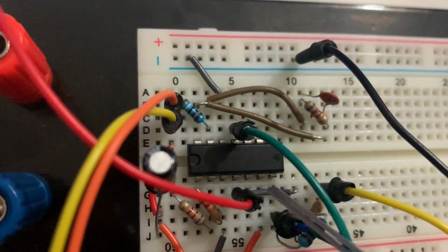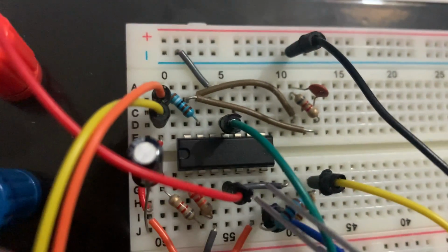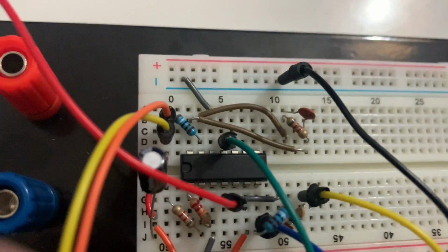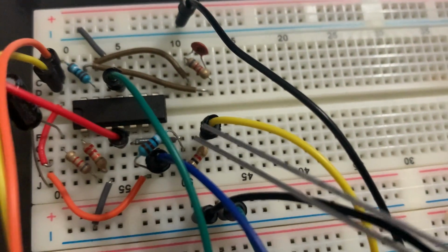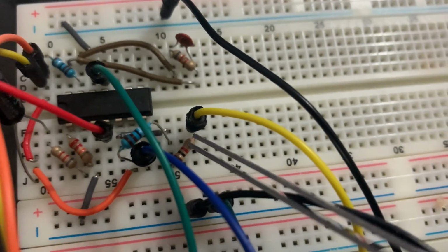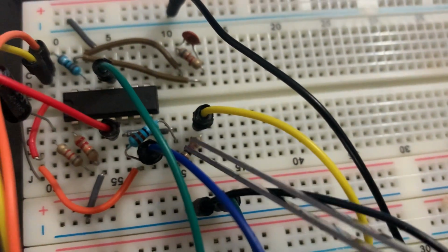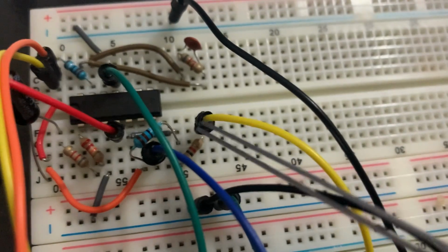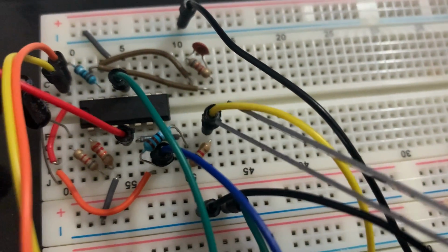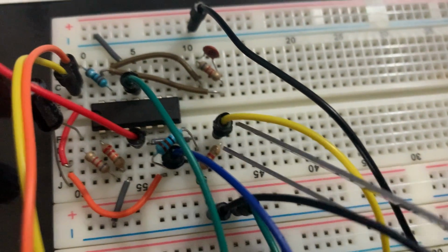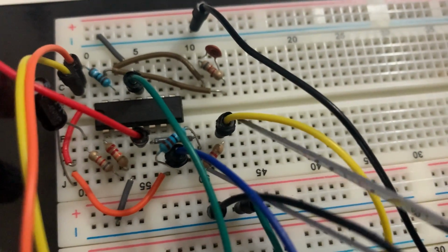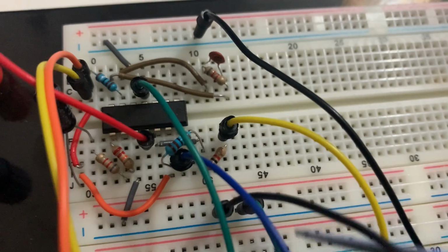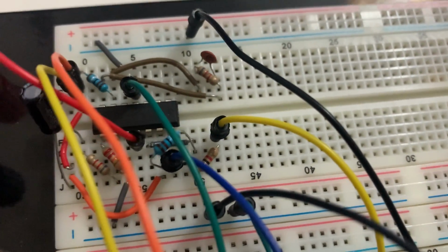This is connected back to the positive input, the gray line here, and also this VF is connected to the 1 kilo resistor and then connected to the V reference. So this generates a constant 1.8 volt voltage. So it serves as a V reference. So overall, this is a Schmitt trigger.